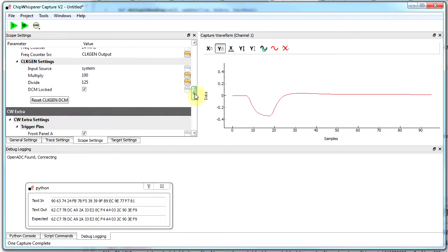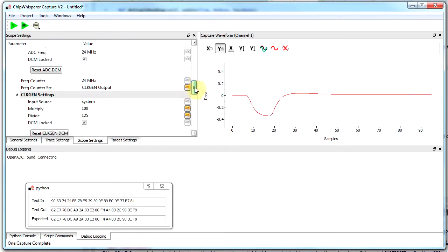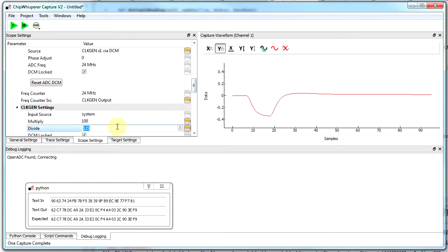So what's kind of interesting is now we can look at, okay, well, what happens if I run the system much faster? So if I run the system at 40 megahertz, you can look at how the power consumption is changing, or if I run it at, what's this, 75 megahertz? Again, we can keep going.